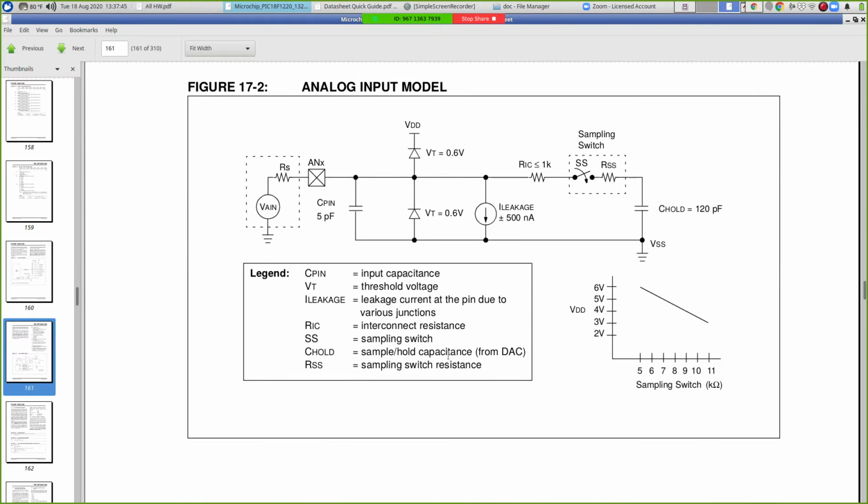And then here's a picture of what the actual analog converter looks like. So here's that analog input voltage coming in here. It gets loaded into a capacitor over here. So when you're acquiring the signal, that input signal coming in on an analog pin goes through this switch and charges up a capacitor. Capacitors, remember, will hold a charge.